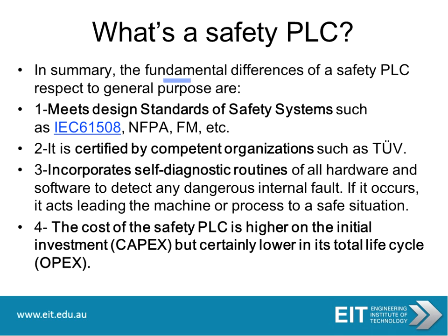Now, in summary, the fundamental differences of a safety PLC with respect to a general purpose one are: one, it meets the design standards of safety systems, such as IEC 61508. It is certified by competent organizations, and incorporates self-diagnostic routines of all hardware and software, so it will detect any dangerous internal fault, and if it occurs, it acts, leading the machine or process to a safe situation. Now, the cost of safety PLCs is higher on the initial investment, the CAPEX, but certainly lower on the total life cycle, the OPEX.